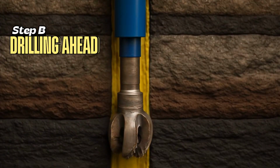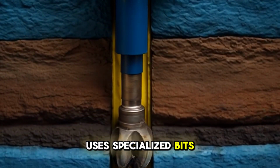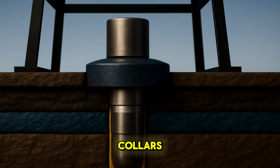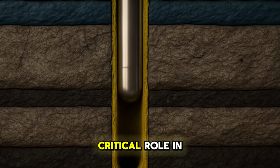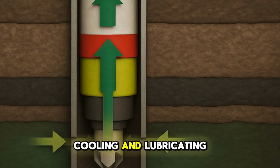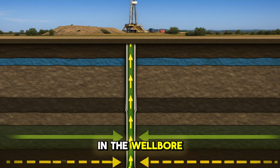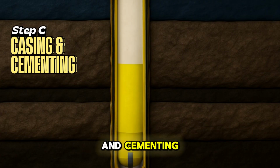Step B, drilling ahead. The drilling process uses specialized bits, PDC, roller cone, or diamond bits, connected to a drill string made up of drill pipes and collars. We circulate drilling fluid, or mud, which plays a critical role in the operation. Its functions include cooling and lubricating the bit, carrying rock cuttings to the surface, and maintaining pressure in the wellbore to prevent blowouts.